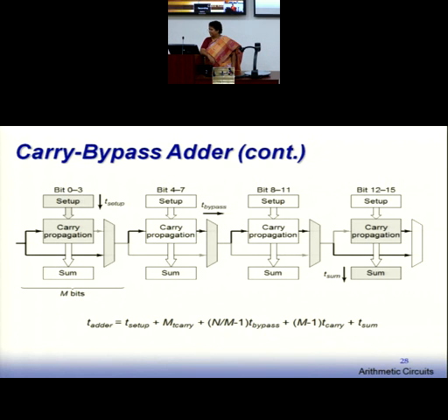Is it clear? No. First stage is generation. So 4 it will take, because all are not propagate. First stage is generate, and then the rest are all propagate. That means carry in will not propagate to carry out, because the first stage propagate function is 0. The 0th bit position propagate function is 0. So if I add them together, P0, P1, P2, P3, you will not get any carry out. It would be 0, because here we are assuming the first bit is generation and the rest is all propagation.